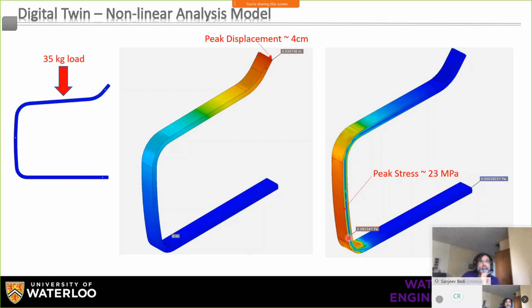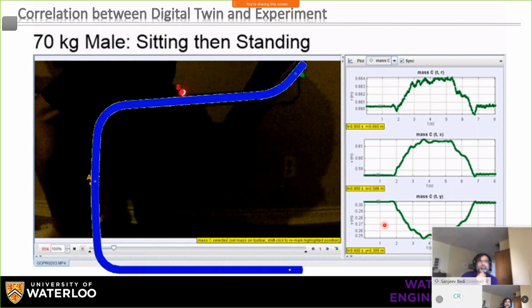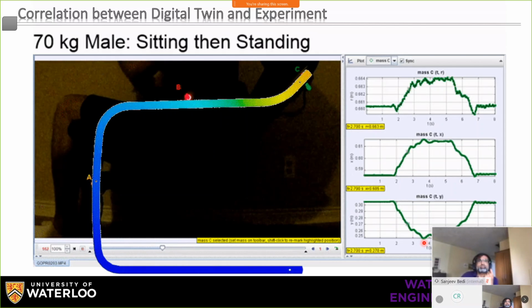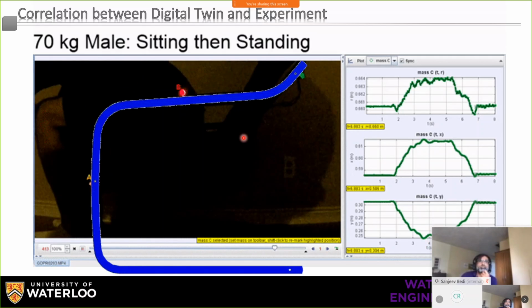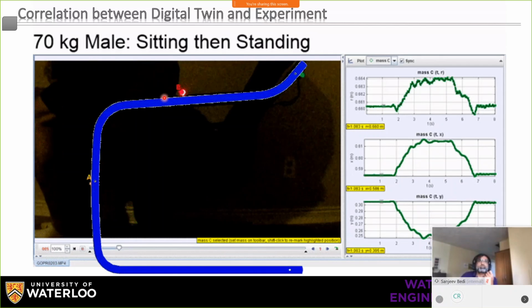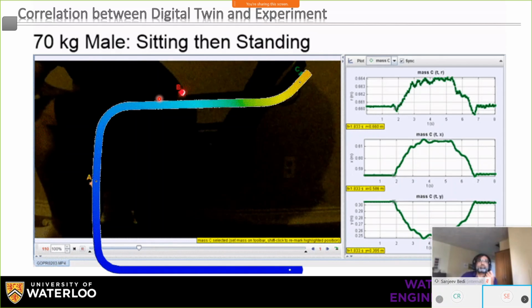I literally Googled the Young's modulus and material properties of bamboo, and there was a variability of about an order of magnitude depending on the source, so I just used nominal properties. So we're pretty close. We might even have students perform a simple experiment to actually calculate Young's modulus of the bamboo, because it could be reinforced at the surface or different in the middle. But as of now, I haven't looked at it in detail. Using nominal properties for bamboo, we get 4 centimeters versus 5 centimeters, which is fairly close.